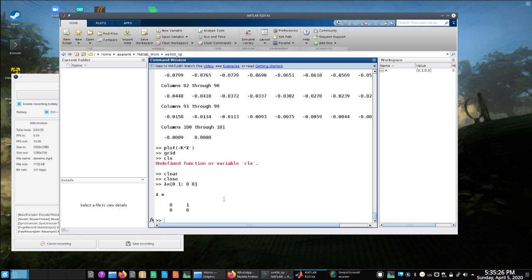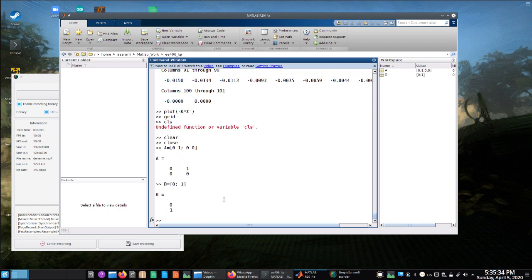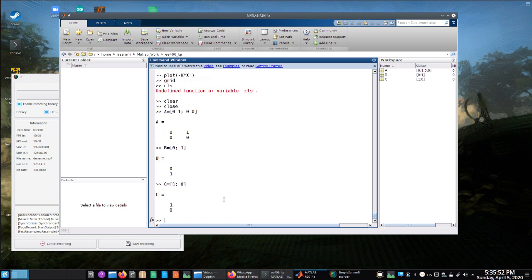Okay, so I will try to also show these matrices for you. B was equal to 0 and 1. It's a column matrix, right? And let's say that our system's output, in fact, we will observe all the states. So this is not very important, but we can select our first state as our output of the system. Sorry about that. That's not correct. We should have C is equal to 1, 0, and D is equal to 0. Okay, so let's construct our system.